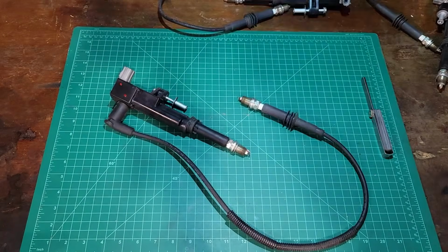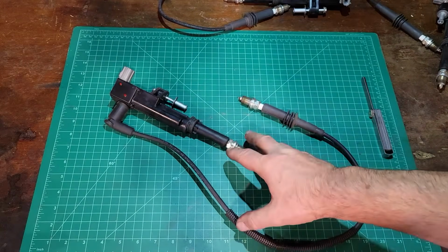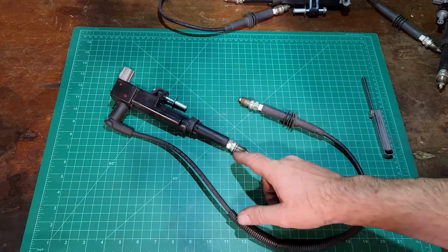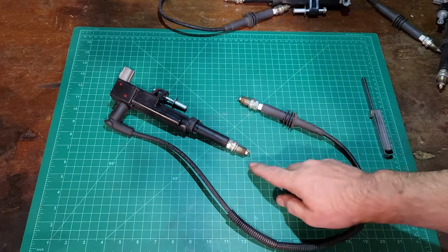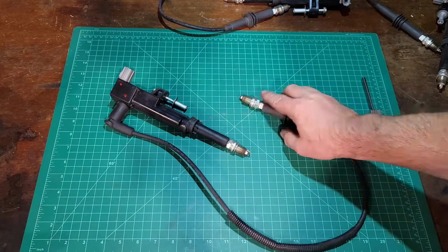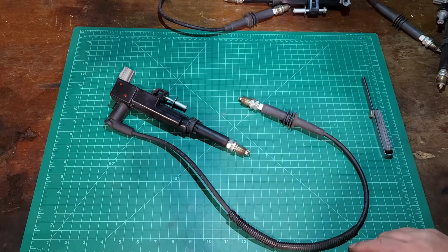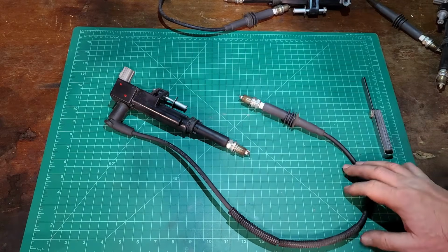This is coil number 2. I'm calling it coil number 2 just for identification, but it controls cylinder number 3 and cylinder number 6. This was 36 thousandths. This is 35 thousandths. Again, 43 thousandths is the spec. The wire was 6,840, so that wire's in spec.